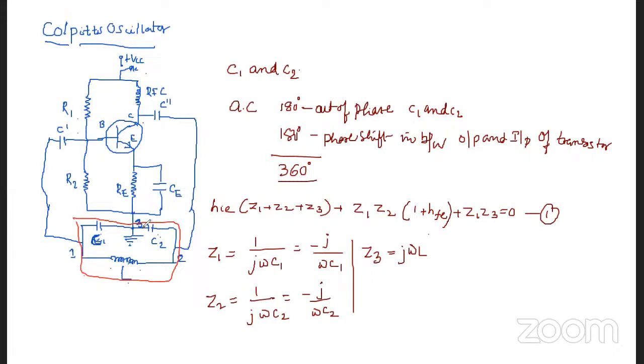So that is the only difference we have in the circuit diagram of the Colpitts oscillator as compared to the Hartley oscillator. In the Colpitts oscillator, R1, R2, RE are the dividing resistors, which will keep the oscillator at its operating point. And here C double dash prevents DC and passes the AC signal, which is supplied to the tank circuit.